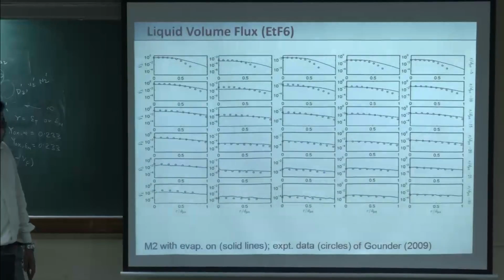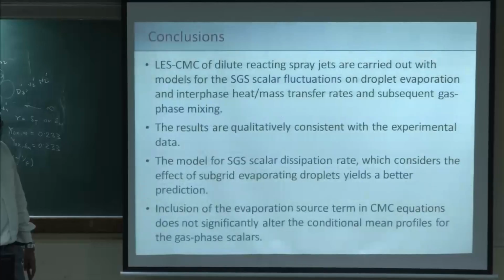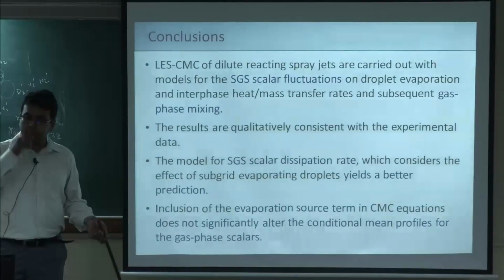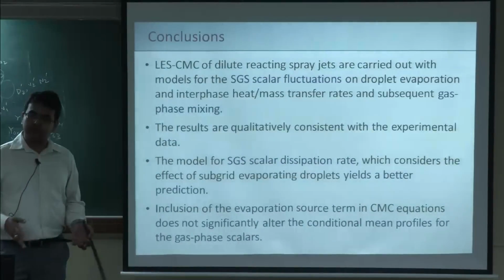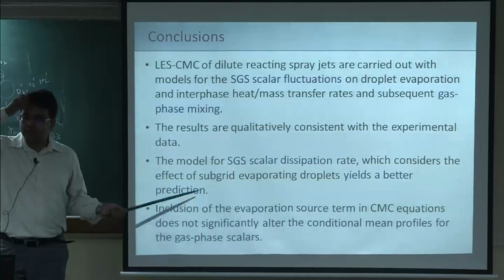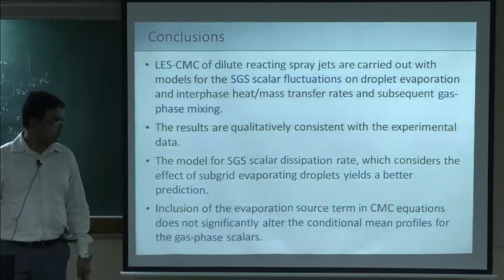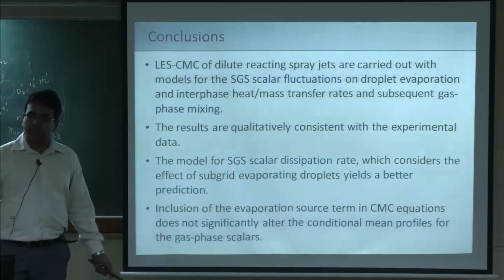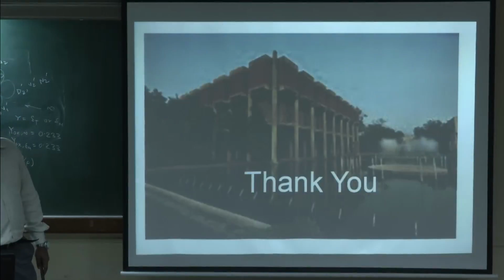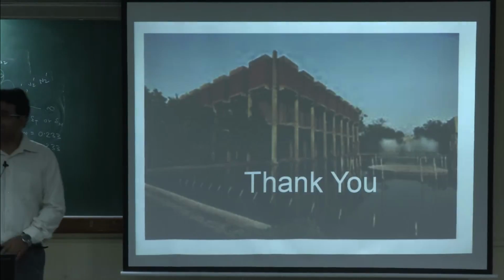So, liquid volume flux. Here actually we tried to evolve from the Mortensen and Bilger CMC equations for multiphase flows, and model the conditional evaporation rate and the conditional scalar dissipation rate, and the predictions are reasonably okay. So that is the conclusion. So thank you.